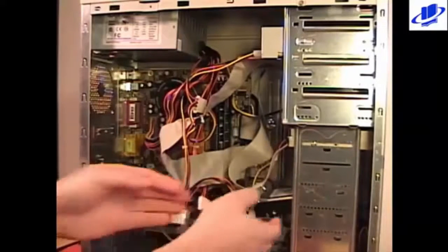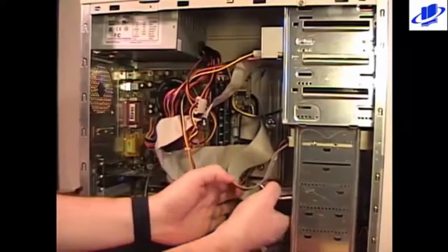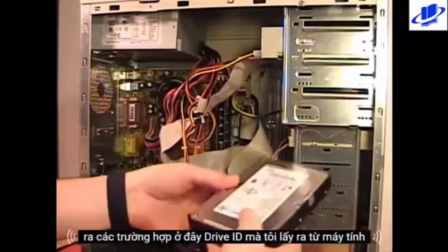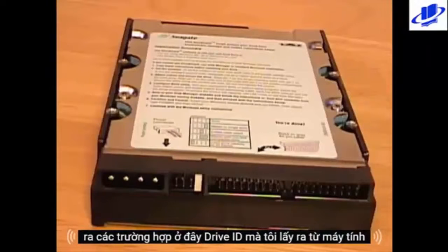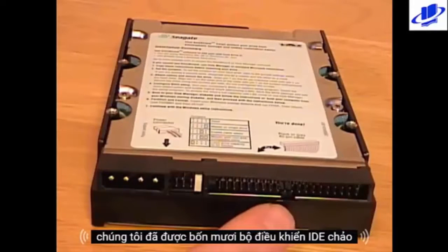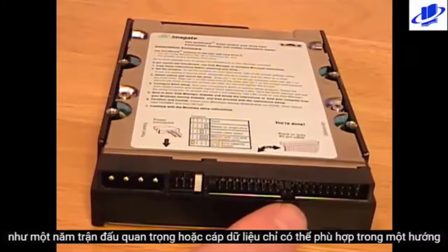With the screws removed, I can carefully move all the components out of the way and then slide the drive out of the case. Here's the IDE drive that I removed from the computer. Here we have the 4-pin Molex power connector. We have our 40-pin IDE controller connector. It has a keyed notch here so our data cable can only fit in one direction.